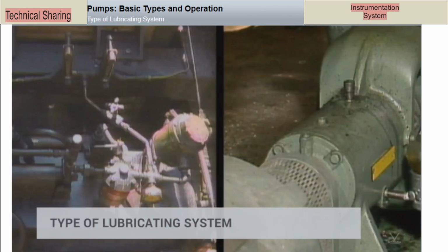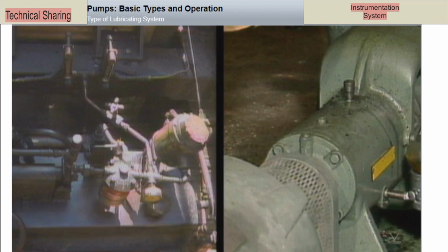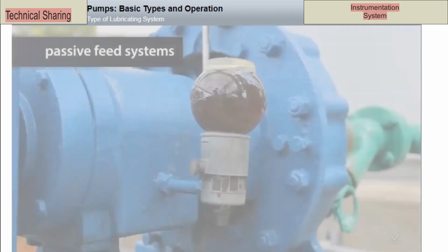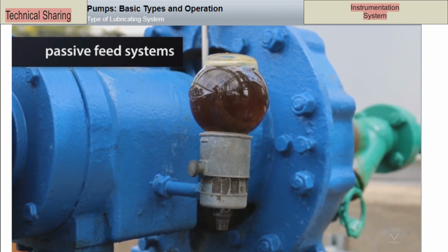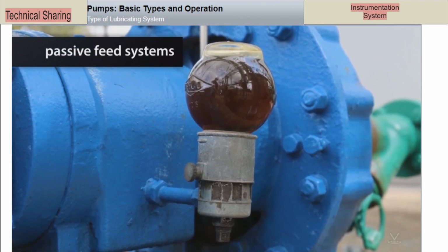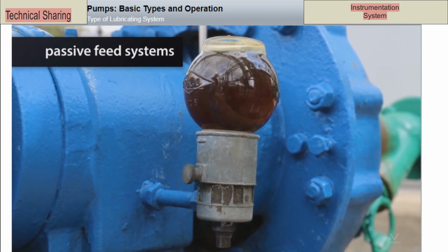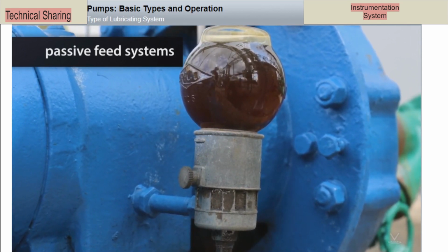Types of lubricating systems. There are two general types of lubricating systems, passive feed systems and forced feed systems. Passive feed systems. Passive feed systems use delivery methods such as gravity to deliver lubricants to the bearings. This constant level oiler is one type of passive feed lubricating system. The oiler has a small reservoir of oil that drains by gravity into the bearing. Another passive feed system is used on bearings that use grease as a lubricant. Grease is supplied at periodic intervals through a grease fitting on the bearing's housing.